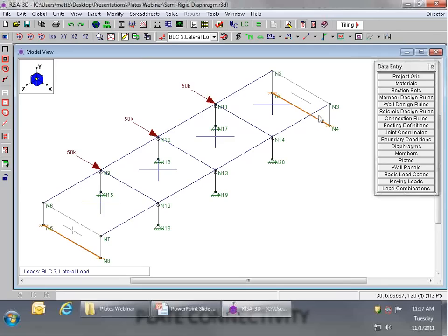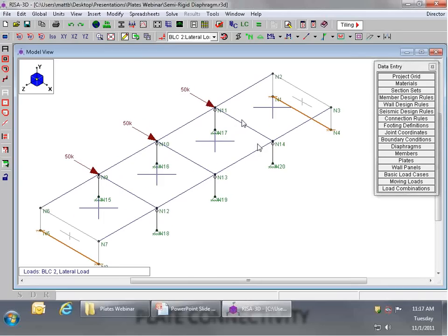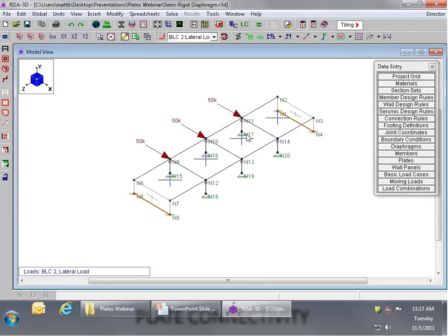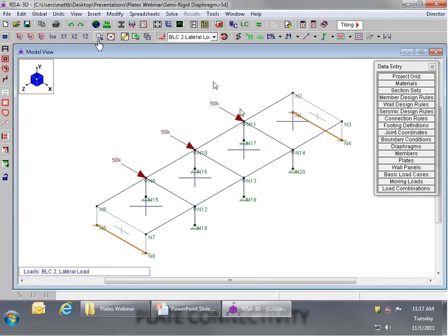Similarly, if I had shear walls running in this direction, we would want them to be fully attached to the diaphragm even during a seismic event. Now note that I have these pin columns, so the diaphragm is just going to be rolling along on top of these. They're not really going to have any additional impact here.